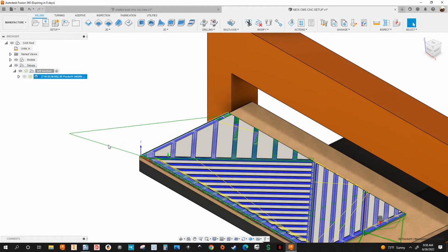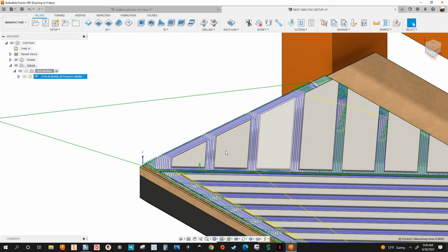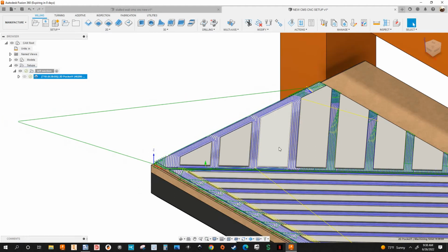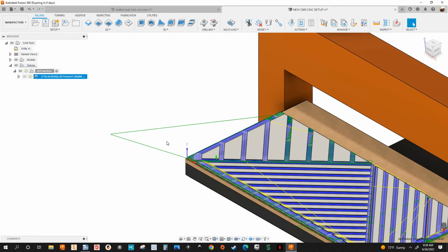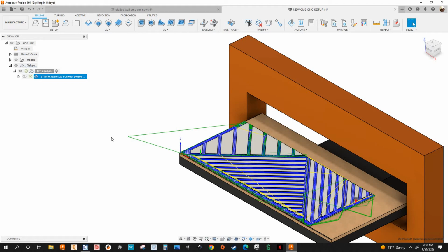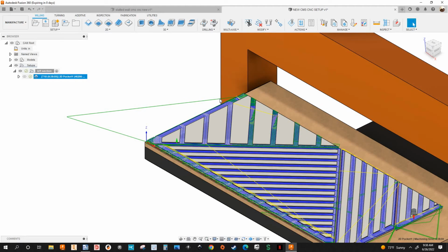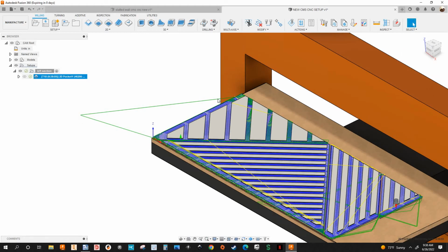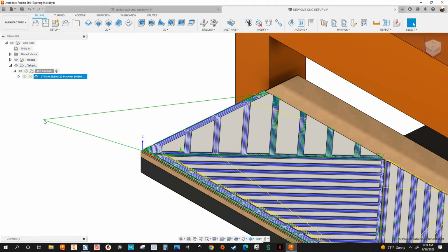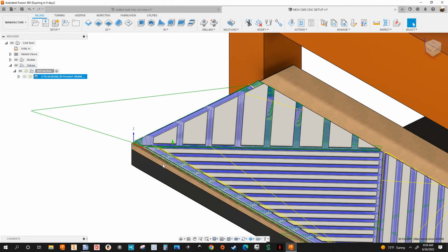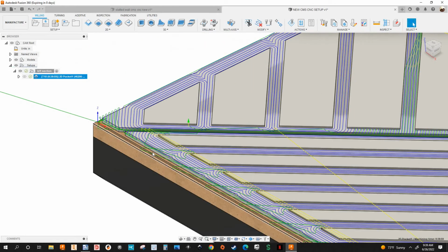Okay, see that? So it's not gonna machine these parts right here. So it had to be a bug. But you see these green lines. That's actually a toolpath. So I'm gonna get an over travel error on my screen on that machine. So see, it's gonna machine here, and the tool's gonna stay down. It's gonna machine air, and then it's gonna go here. So I have a lot of over travel going on here.